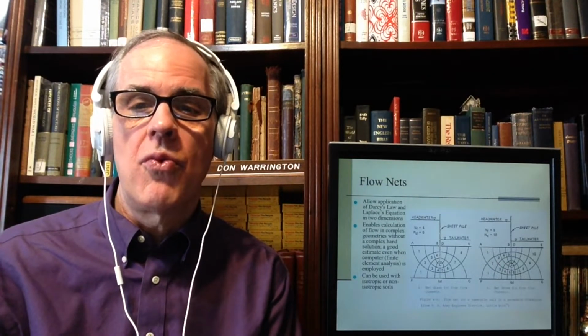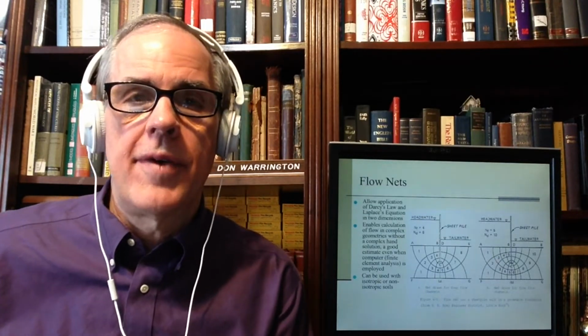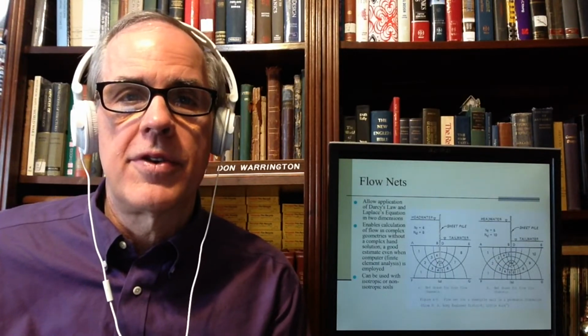Basically, they're a way of actually replicating it. They do several things for us. One of them is they show us which direction the flow goes in, and give us an idea of how it gets from one place to another. Second of all, it basically reduces a 2-dimensional problem to a series of parallel 1-dimensional problems. Number 3, it's a way of doing Laplace's equation in a very simplistic way, and surprisingly it's worked.